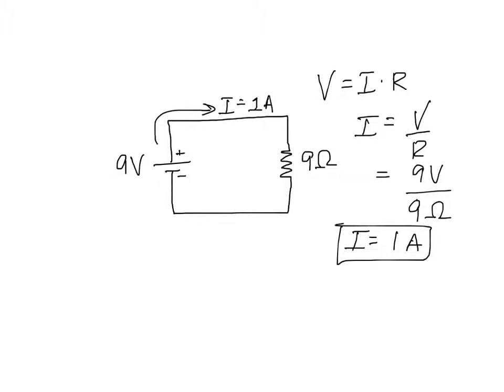So I know now how to size the wire. When you go to Home Depot, you can actually buy different gauge wires, that's different thickness, based on its usage and how many amps of current you're going to have running through it. And you can now also size a circuit breaker based on how much current that wire is designed to carry. So that's a simple series circuit. That's pretty straightforward. Now we're going to talk about how to analyze a circuit where the resistors are in parallel, and we'll go through that.